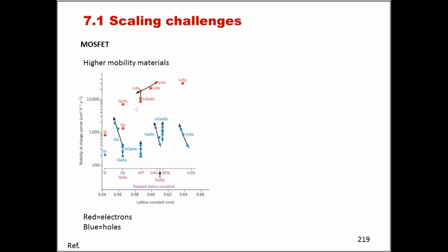Remember though, and I should stress this, as we've said some time ago, one of the reasons that the semiconductor industry is based on silicon is not because silicon is a great semiconductor. As this plot is showing us, this is not really the case. Silicon is not really a good semiconductor, as we can see here. The mobility is not great. But the reason we use silicon is because it has a great insulator, a great oxide that comes with it. And that's why the tandem silicon and silicon dioxide have effectively driven the microelectronic and nanoelectronics revolution.